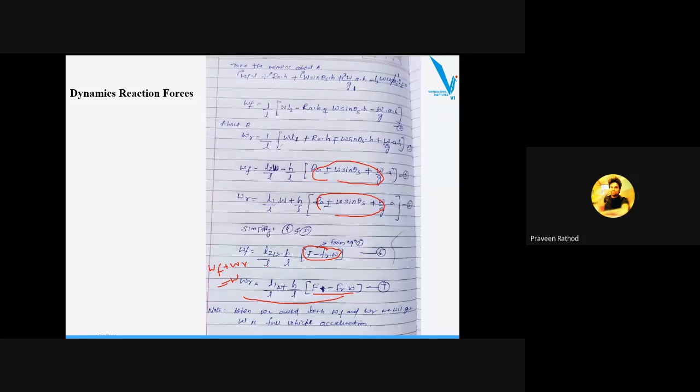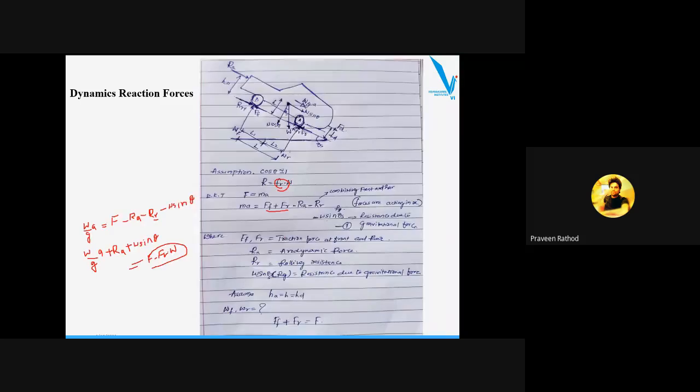Just do this step. So you do this step, add both of them. Try to write down the equation on your own by drawing the diagram. Just draw the diagram. If you consider the vehicle moving on a flat road, there are very simple equations. Just try it for a vehicle moving on a flat road. On a flat road you will not get resolving forces. Only one force will come, W, that is mg. And two reaction forces will come, WF and WR, similar, and the dimensions will also be the same, rolling resistance and so on will be similar.